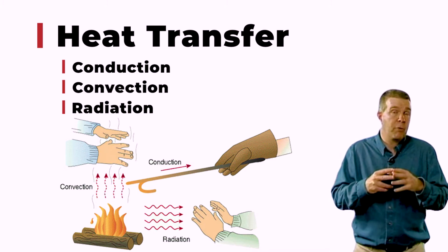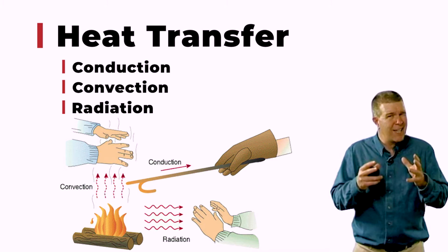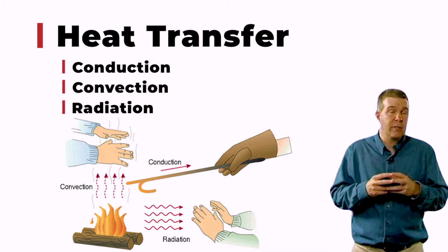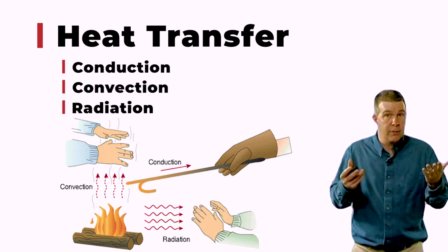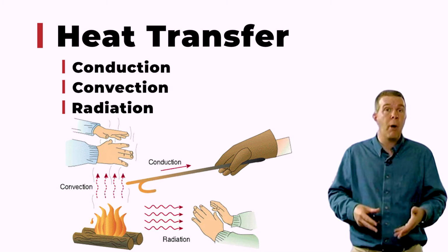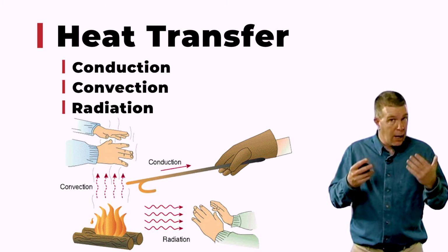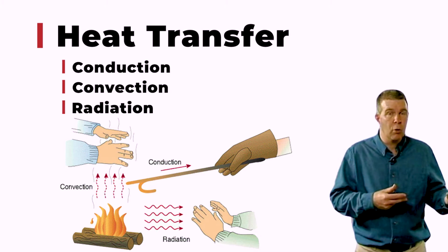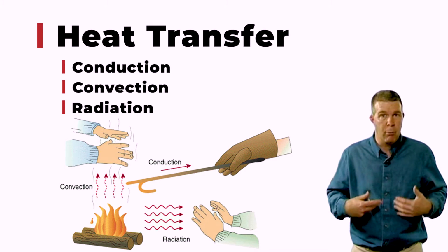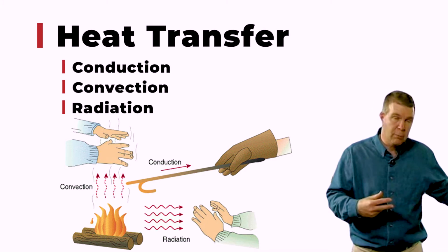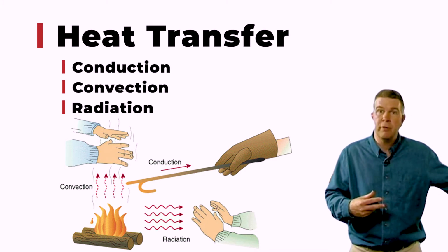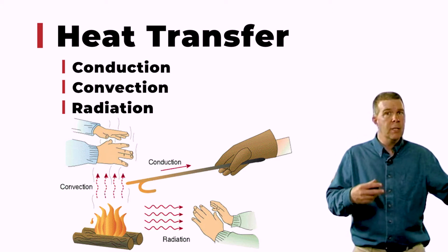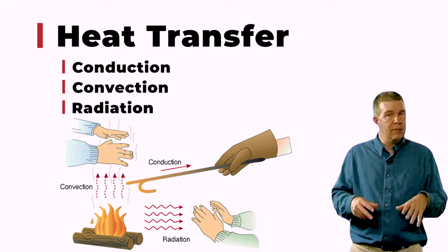Okay, and a lot of people think, well, heat rises. That's not exactly true. Heat doesn't necessarily rise. Warm air rises. What heat does is goes from hot to cold. Okay, hot to cold. So if you're standing next to a cold wall, the heat goes out of your body into that cold wall, and that's a movement horizontally, but it's heat moving in horizontally nonetheless. So convection, remember, heat's from hot to cold.